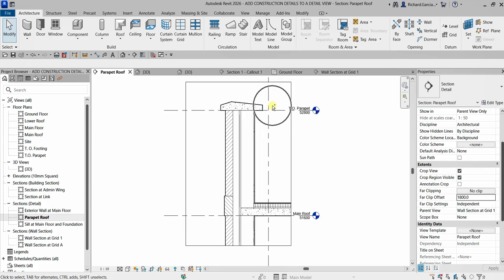You see, it now hides this area that we don't need. A while ago this was 8,000, so look what will happen here. It's showing elements behind, right? I don't want my view to be far like that. I just want this to be 1,800 so that it's hidden. So the far wall is no longer visible in the view.